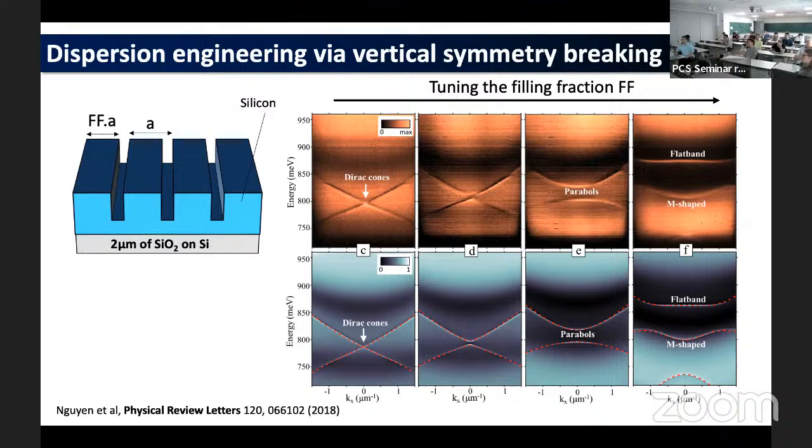That's why we end up with some strange values, like 0.75, 0.72, and 0.58. But actually we target 0.6 and 0.7. What is the actual lattice constant in microns, nanometers? So the period is 300 nanometers, because we target the wavelength in the telecom range, 1.5 micron, where silicon is transparent and has a high refractive index.